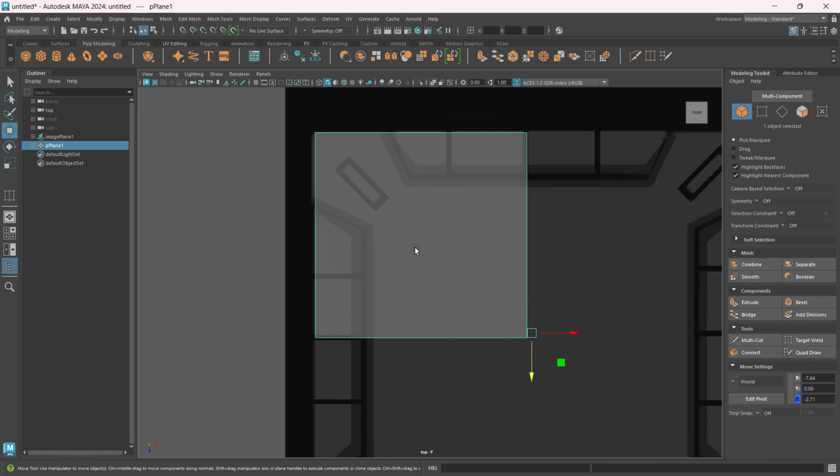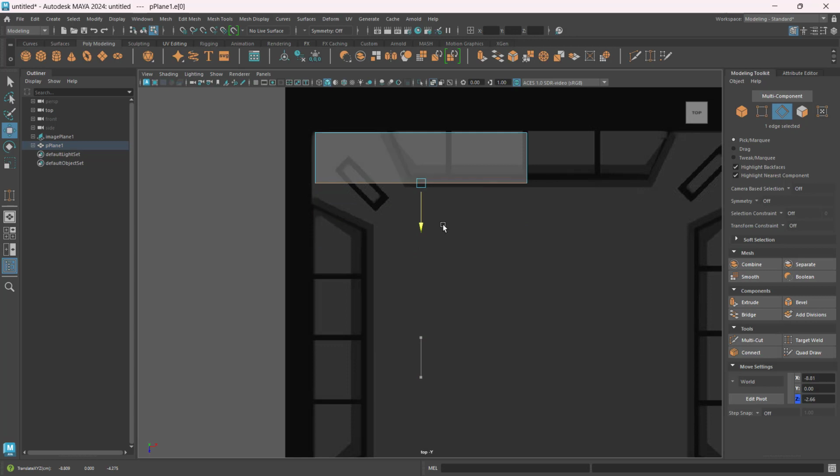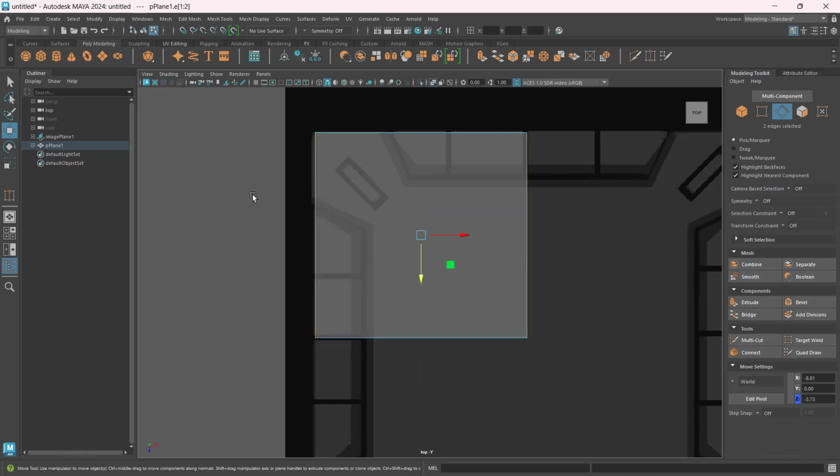You can do several procedures with this. For example, if you still remember your modeling procedure in your base mesh polygon, you can do something like this. Oops, sorry. I can select these edges and then I can just connect them and then press Enter, W. I can drag it here for that corner. And then I can do the same here, the horizontals. I'll just do another connect, Enter, then W for the move tool, and there it is. Now I can just go to my vertices and drag that vertex and have that created.